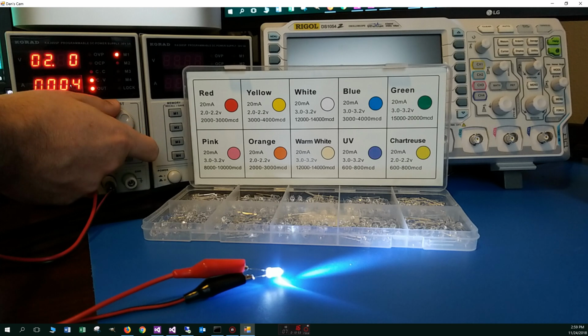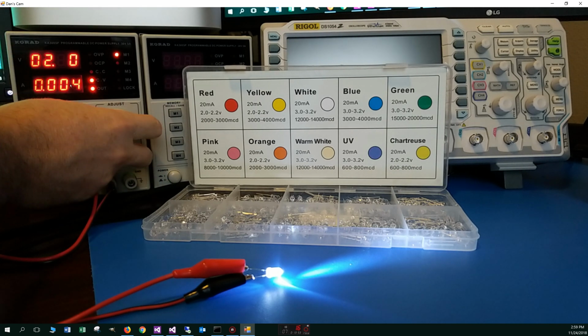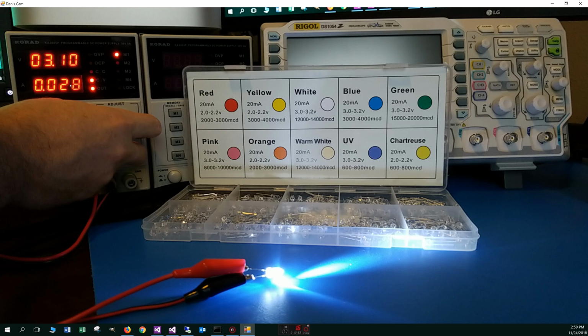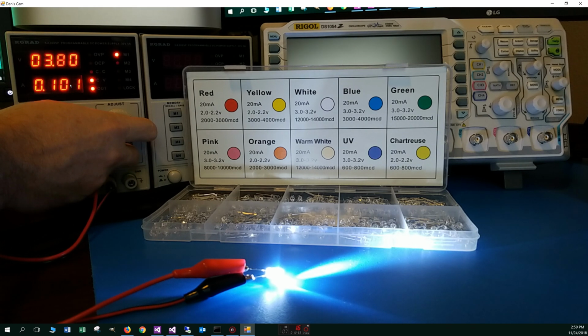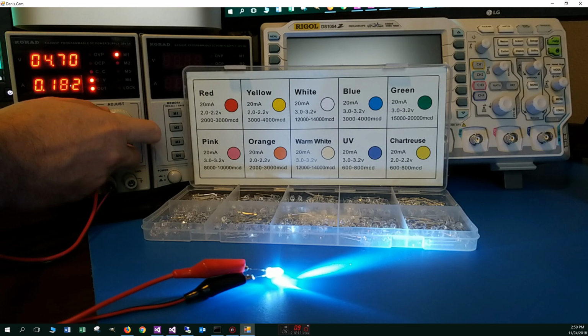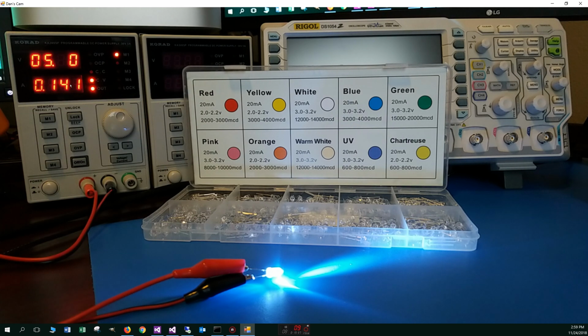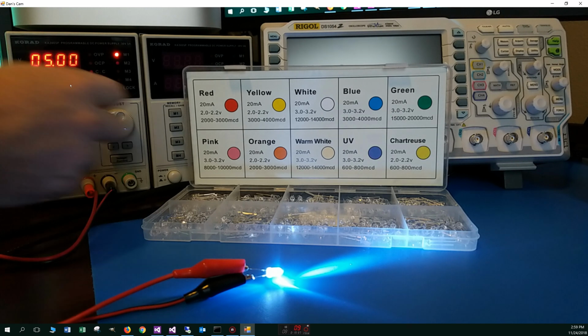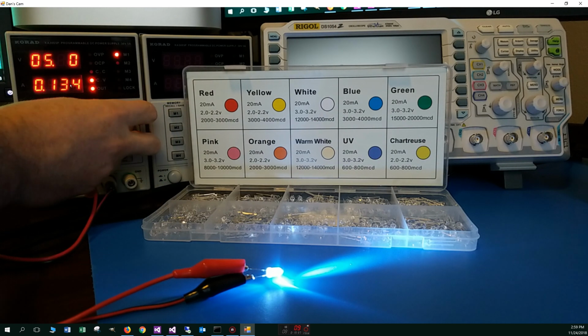But now, the power supply is going to output a maximum of 1 amp, and as we decrease this, the light's going to become dimmer. We're going to see the same thing going on there. But now, we've got some serious pushing power behind this thing. And you could see the LED is getting much brighter. Now the LED is starting to dim out there. Okay, at 5 volts, we're pushing 137 milliamps through. Let's keep cranking this thing up here.